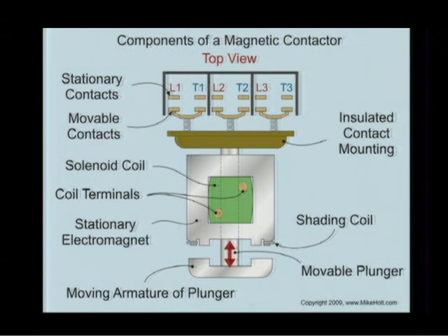One of the words that always bothered me is when you call it a contactor and you call it a starter. Steve? I was just going to say, on this type of frame that you have on the screen here, they want you to be careful what position you mount it in, because if you mounted it upside down, on some of them, they wouldn't open.